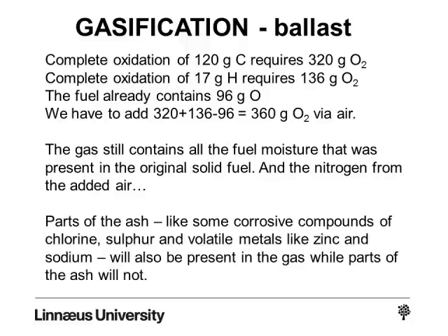And there is more ballast. Parts of the ash, like some corrosive compounds of chlorine and sulfur, and the volatile metals like zinc and sodium, and alkali sulfides and so on, will also be present in the gas. So this gas is not all free from ash components, and the gas still contains all the water that was present in the original fuel.